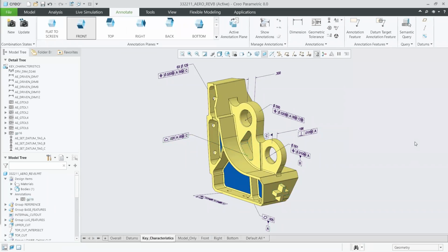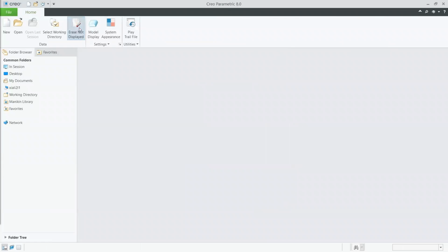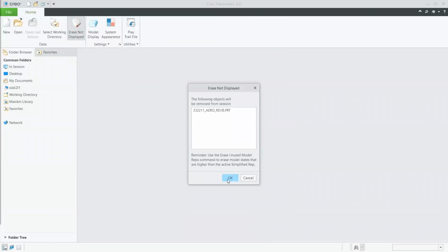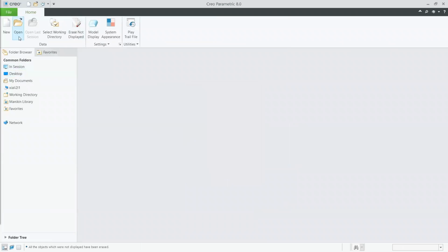That's a new function that supports all types of standalone annotations, excluding surface finishes. So with that, it's much easier to go through and select multiple different semantic references, even in these more complex shapes. And of course, with that, less time is required now for the reference selection task that you might have to do.